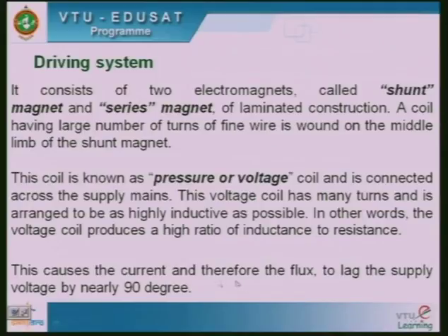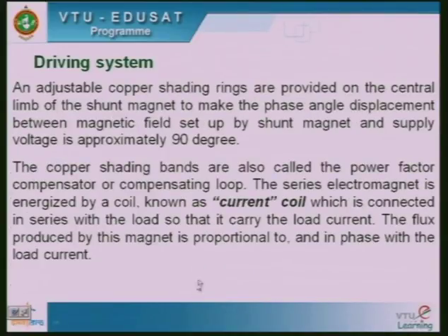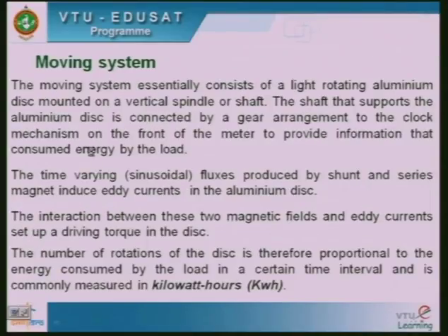You are using that copper shading band to make the flux lag the supply voltage nearly by 90 degrees. So, by using that copper shading band, you are making it happen, that is, current lags the voltage by an angle of 90 degrees. That is in the driving system.